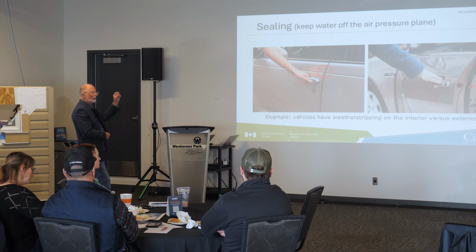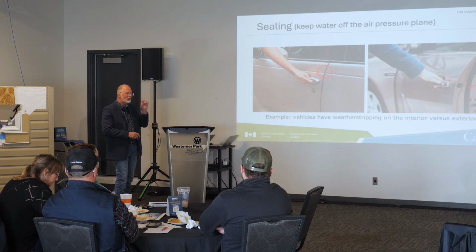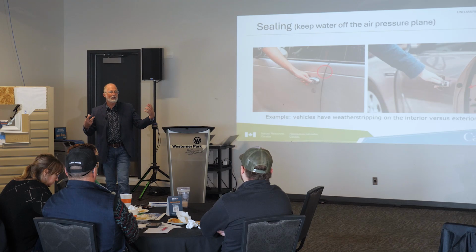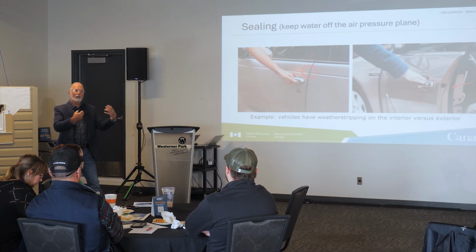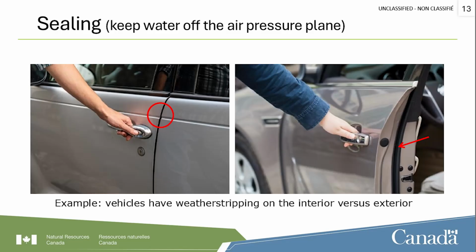So there's an example of first and second plane of protection. The air that goes into that cavity pressurizes the cavity. So if it's the same pressure in the cavity as it is on the outside, what's causing the water to enter that joint? Nothing. It's not going to go in there. And if a little bit goes in there, there's no pressure difference. So all it does is go in there and fall down by gravity and drop out the bottom. So if we installed windows this way, would they perform better or worse?